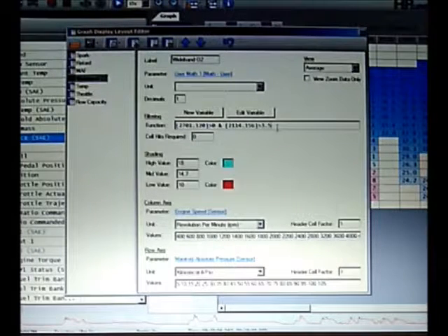They're probably getting choppy correction factors that produce a lot of unwanted noise on top of their readings, because it includes the odd deceleration point that you didn't want in there. Now the reason you don't want deceleration in there is because when the car's decelerating, usually the timing will retard.